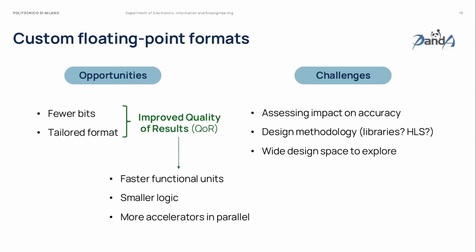The opportunities are that if you have fewer bits and you use a tailored format for your application, you could have improved quality of results because your functional units are faster and have smaller logic. Smaller logic means that in theory you could have more accelerators in parallel in the same area. There are a lot of challenges here. Mostly, you have to be able to assess the impact on accuracy. If you throw away half of your bits, will the results still be valid?